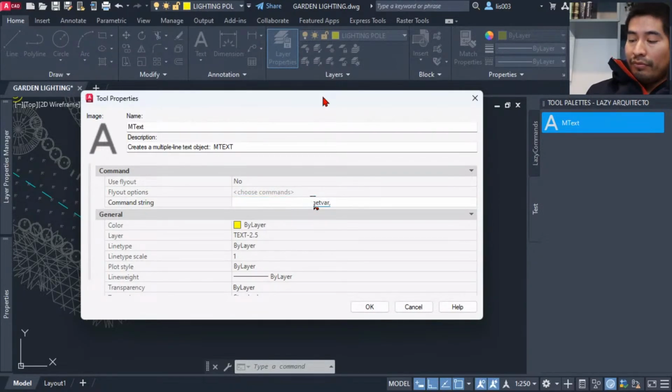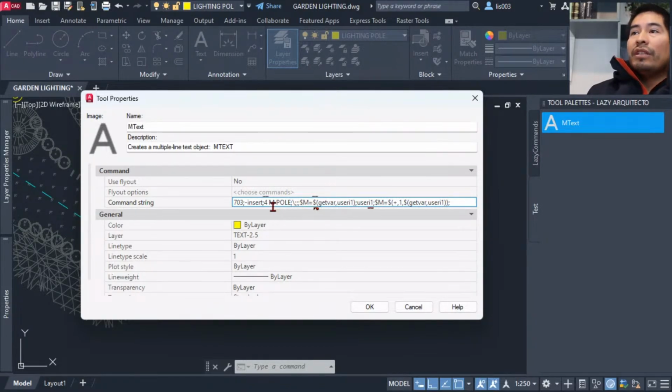Now, since my friend was using spaces to name his block, and macro codes don't like spaces because they can read them as an Enter on your keyboard, I needed to use these quotes for his block name, so that way I could avoid some problems.